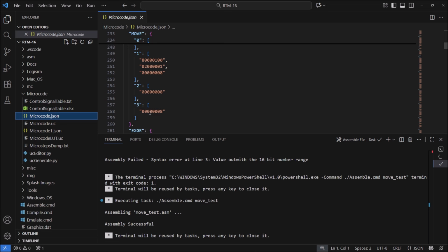Now, as I said, the store command and the load command have already got this microcode generated for us, because in effect they do exactly the same thing. They're just called different instructions. So potentially we could just copy the values from our store and our load, and we can place them in here, and that should be us ready to go.